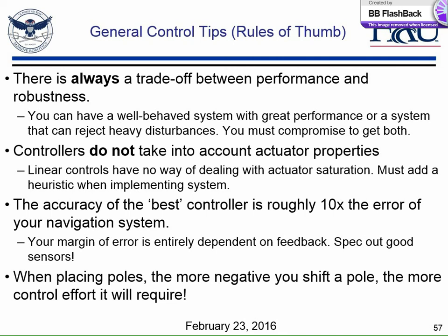Controllers do not take into account actuator properties. This goes back to the integral wind-up that I was talking about. Your linear controller has no knowledge of your actuators whatsoever. In fact, most actuators are nonlinear because you can saturate them. You have some kind of piecewise continuous function, which is inherently nonlinear. So linear controllers have no way of dealing with actuator saturation, and you have to add in a heuristic to deal with that later.